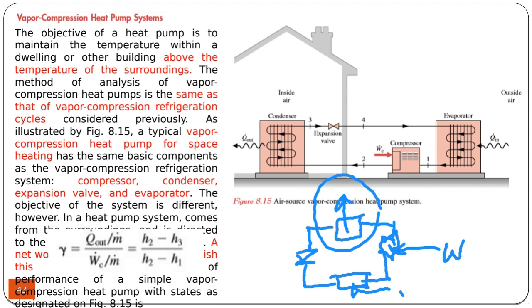So by just changing the mode of operation in your air conditioner, all of a sudden it becomes a heater because you just replace the roles of inside unit and outside unit. Normally, in summertime, the inside unit is the evaporator, which absorbs heat and makes the surrounding cold. And the external unit, the outside unit, is a condenser, which rejects heat.